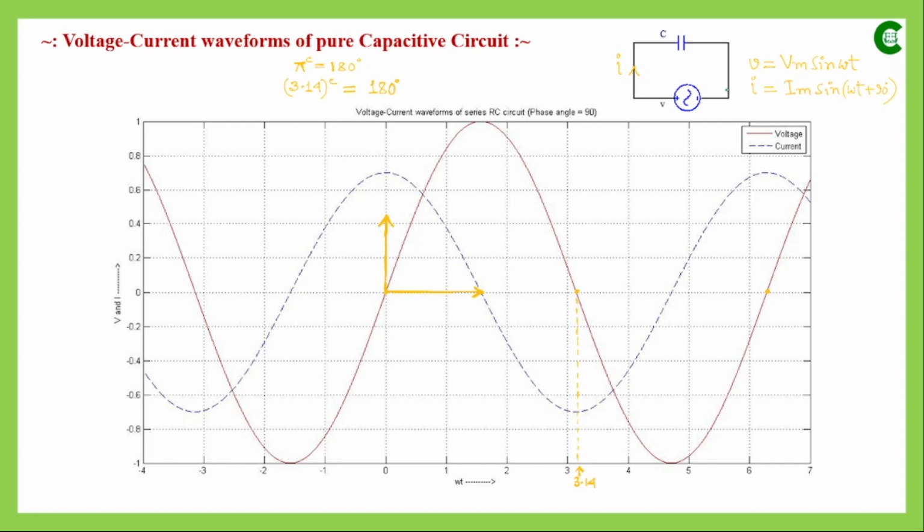So this time we are taking the voltage as reference. So V will be represented as Vm sin omega t. We can take I also as reference, the way we took for the inductive circuit. So V is equal to Vm sin omega t, and with respect to that, now current will be represented or plotted. So V first will be plotted, and this is again the origin.